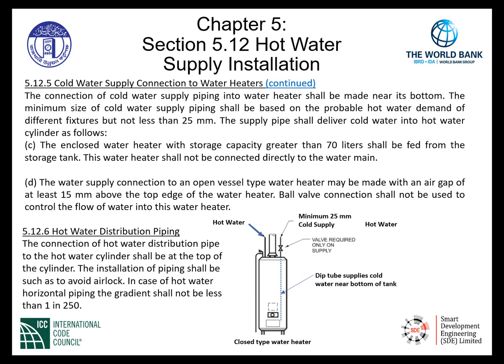We are showing below a closed type water heater. This is not an open vessel. This is a pressurized storage type water heater. And we have a minimum 25 millimeter cold supply pipe feeding the water heater. Within water heaters, manufacturers install dip tubes, and this allows the cold water to supply this particular type of water heater through all the way down to the bottom of the water heater.